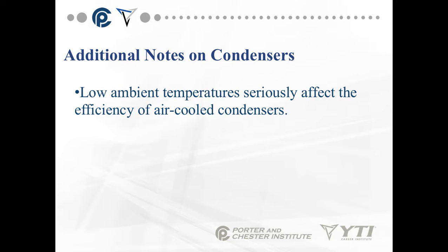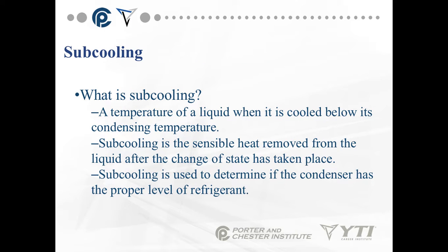Low ambient temperatures seriously affect the temperature of air-cooled condensers. The lower the temperature, once you get below a certain point, the pressures are going to drop in the system. And sooner or later will drop enough that we're not going to get our heat coming off. We're not going to absorb heat properly through the evaporator.